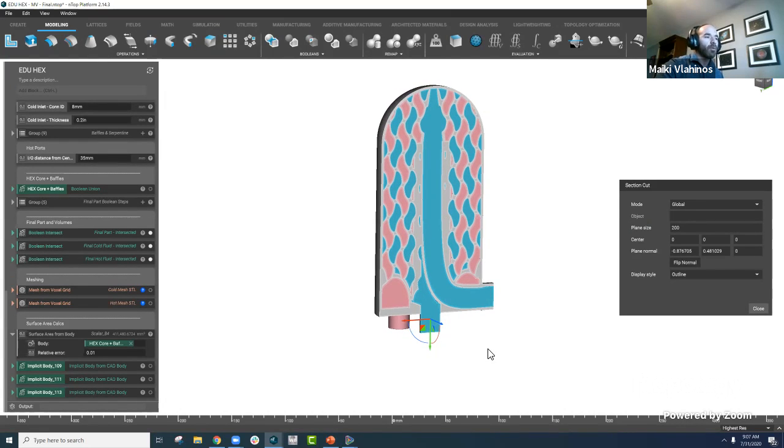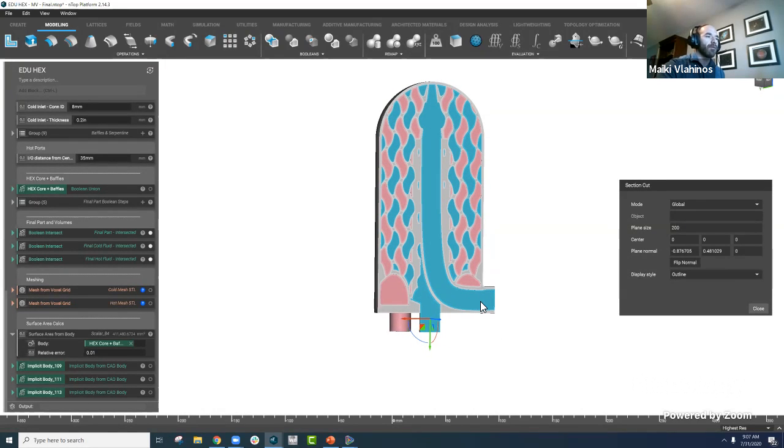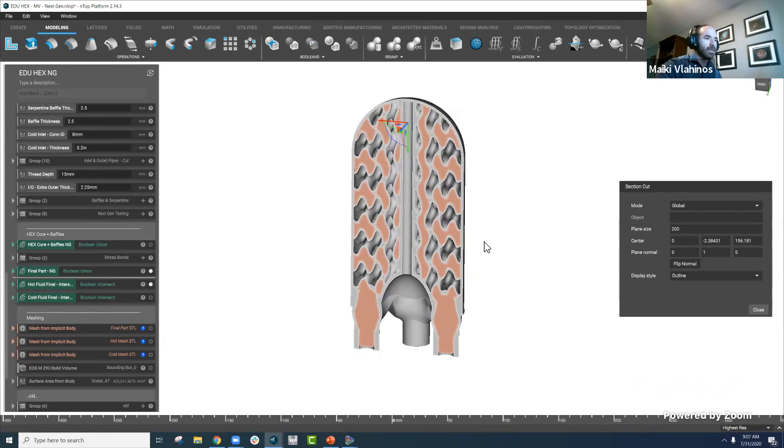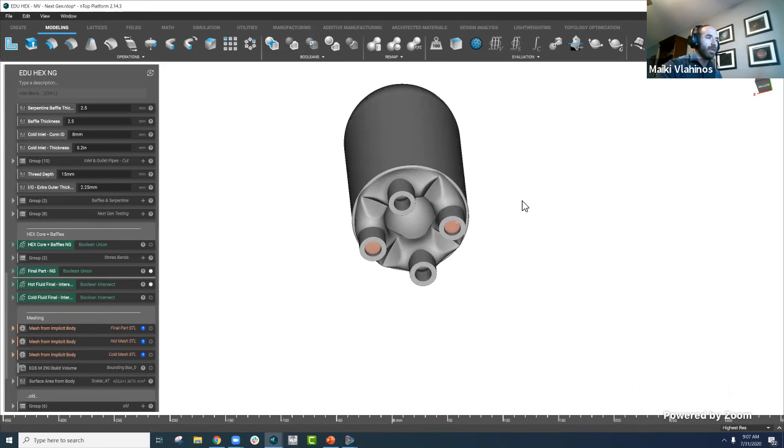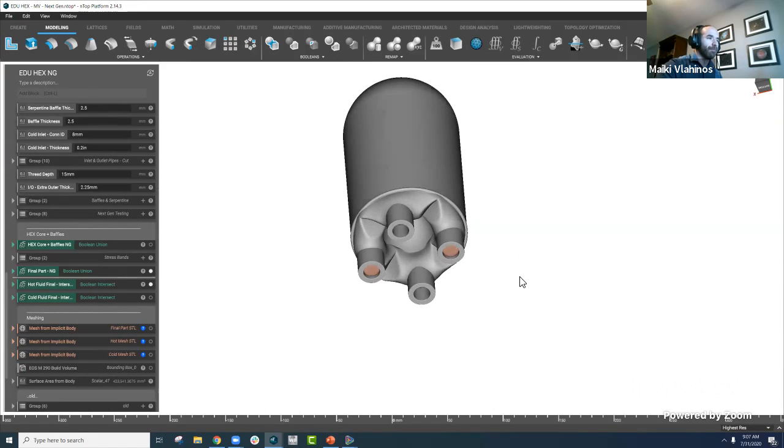So right away we said, okay, let's try and either improve the flow of the cold fluid domain because we saw such a high pressure drop comparatively, or maybe we can try and design it so we have a very similar flow path as we did with the hot. So that's how we landed on this multi-ported design with the inlets and outlets there at the bottom.